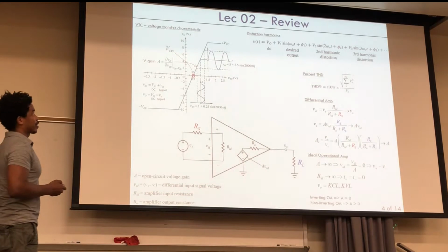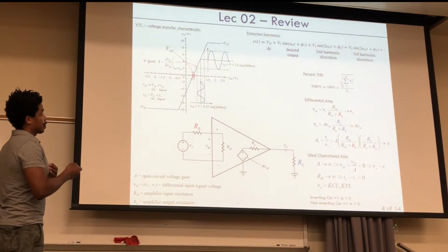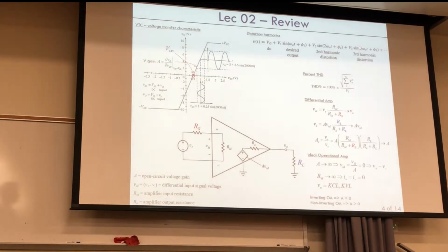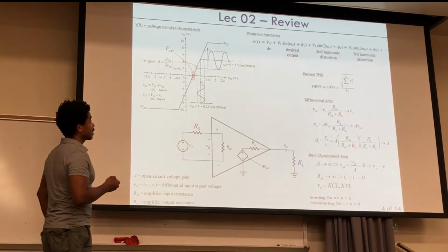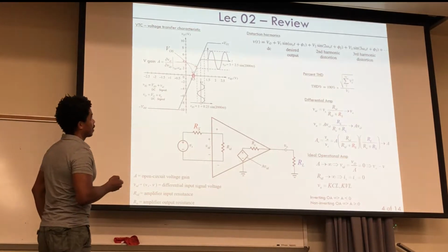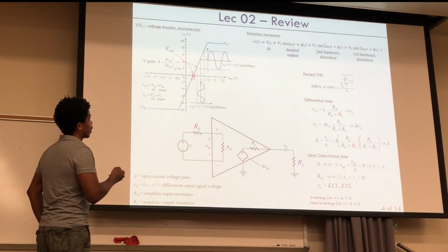And that's also called the spectrum, right? So you might see spectra where here's the magnitude of the spectra, but it's at that frequency, that particular harmonic. So you have a DC component, your desired signal, and all these interferers right here that are interfering with your nice signal that you really want. You can describe that with a percent THD, total harmonic distortion, okay? It's 100% times the square root of these things squared, so from 2 on, you're just squaring all those, divided by that one, right here.